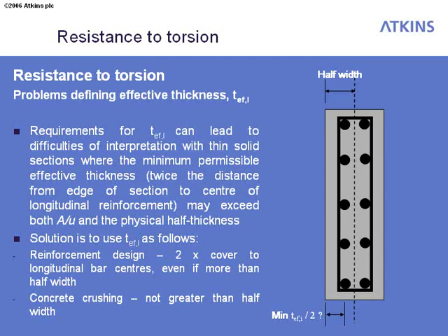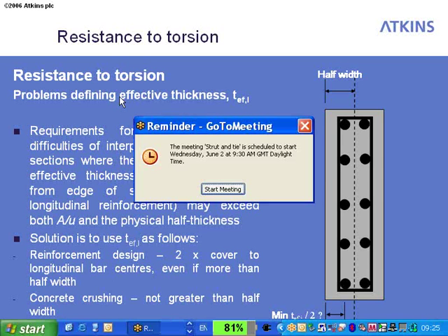In fact, I had a discussion with the project convener for Eurocode 2 about it, and he said, surely when you analyse your decks with these M-beams, pre-tension beams, the torsions are so small that you just neglect them. I said, well, we can't neglect them. You're right, they are very, very small, but then the resistance to torsion is also very, very small. So when you apply them, there's still a significant effect. It wasn't intended really to ever apply it to something as small as this.